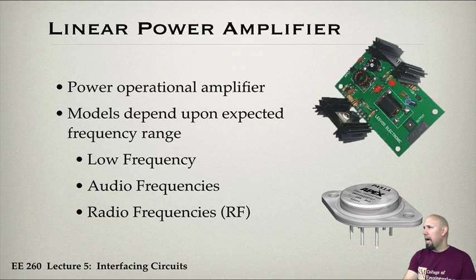Here's another power amplifier. Okay, so notice often you'll see a lot of heat sinks when you work with power devices. So a heat sink, basically these devices can get hot. Okay, and so a heat sink is used to take that heat away. If devices get too hot, they can fry, right? So even though their voltage is in the right range, they can accumulate heat, and that accumulation of heat can cause the device to fry. And so it's very common to have the devices connected up to heat sinks that'll take away the extra heat. So it keeps the device cool.